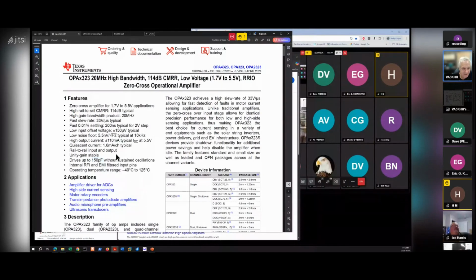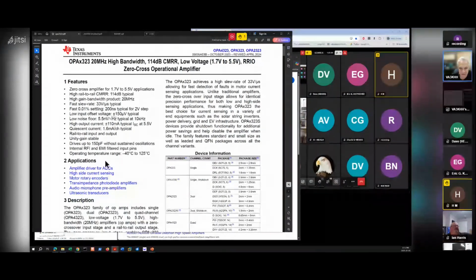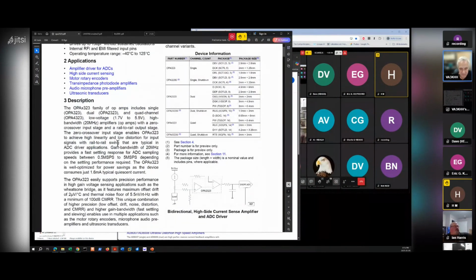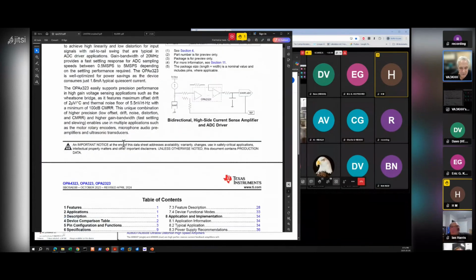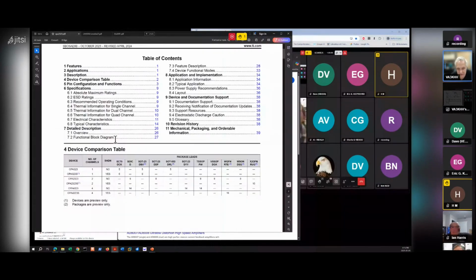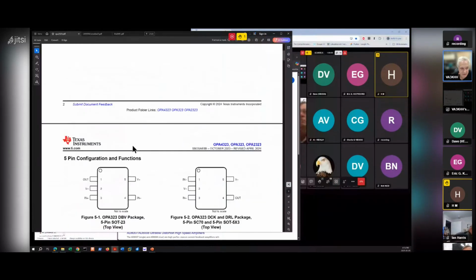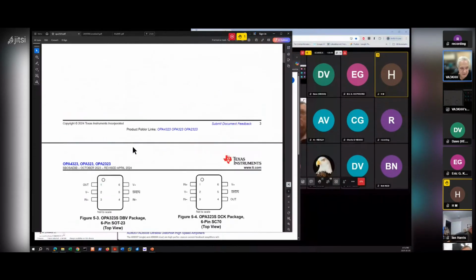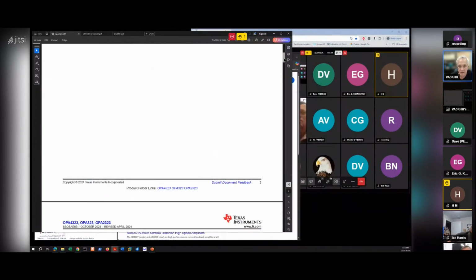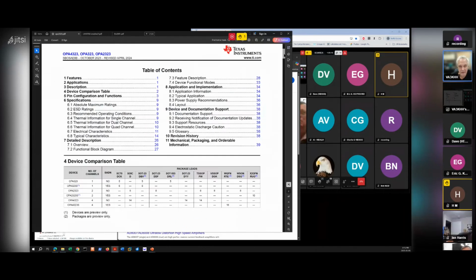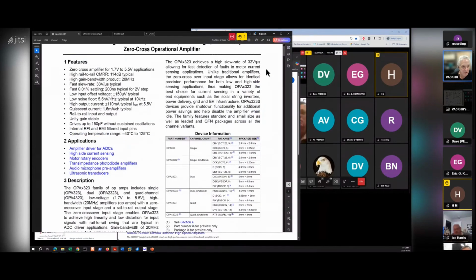It doesn't like high capacitance outputs, right? Because it changes that compensation capacitor value, and it affects that feedback loop. And this is where some people get into trouble. You think, oh, I want to gain 20 dB, but then if you've got a lot of capacitance in there, or you need a higher drive current, then that's not good either.